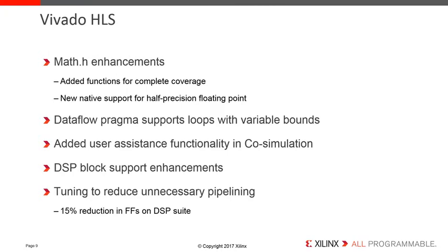There are a number of enhancements in HLS. This includes support for math library functions, dataflow pragma loops, added functionality for co-simulation, and DSP block support enhancements. HLS has also been tuned to reduce unnecessary pipelining that results in up to a 15% reduction in flip-flops being used.